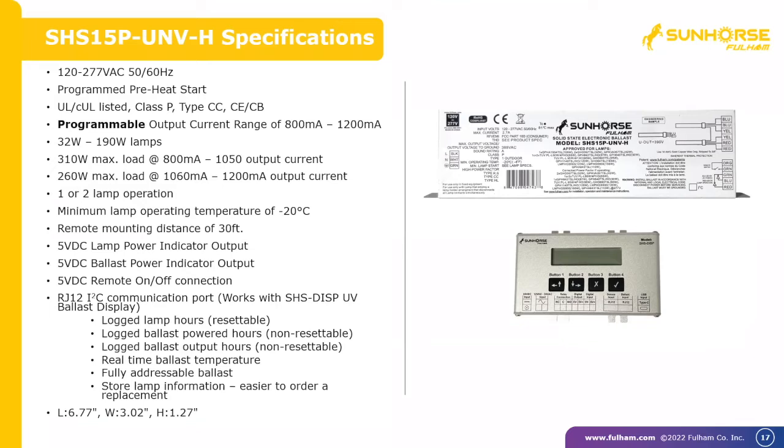The ballast itself also has the capability of interfacing with other customer interfaces and controls that a customer might have. This can all be done through the RJ12 port, so long as the devices have the capability of communicating with the I2C command protocol.